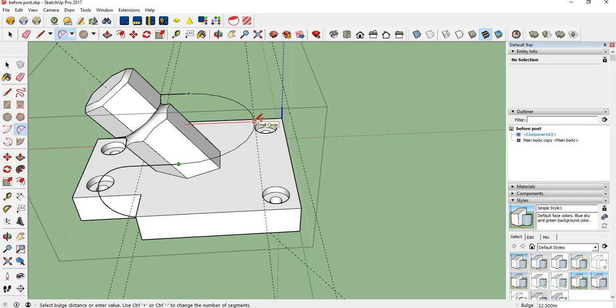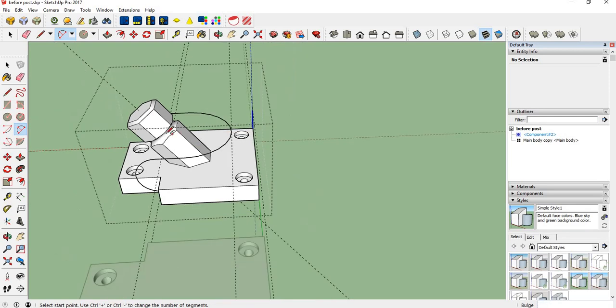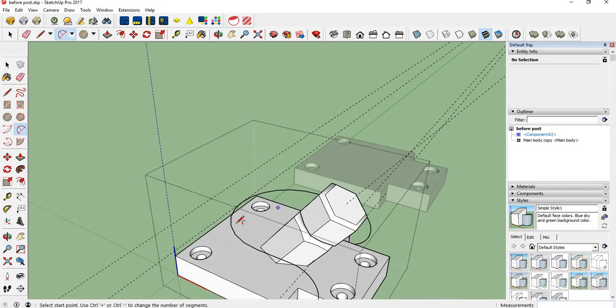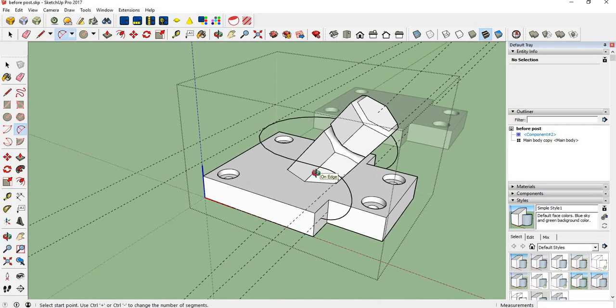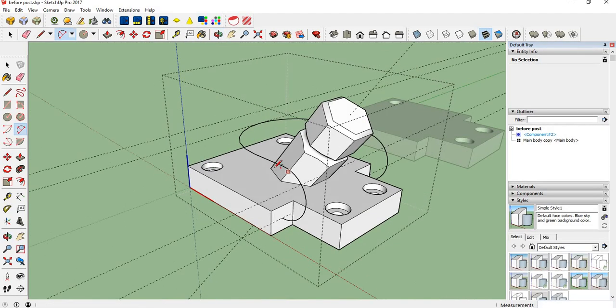And notice we're butted up right against the guide and it says half circle, so that's what we want. Or you can use tangent at vertex. They're both going to be the same because of the way we've done our measurements. That's how you know you've done your measurements correctly, is when it says tangent at vertex and it looks like a half circle, but then you hit the right arrow to make it along the red axis, and it ends up saying half circle when you're connected to the guide. So we know we're golden.